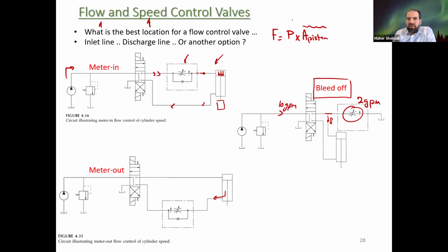We're not changing. Now, if I have the valve here, then the pressure is going to drop from whatever pressure it was before I put the needle valve. I have now some pressure drop due to that valve, so it's going to drop. That means the pushing load in the extension phase is reduced, or it's limited, right?